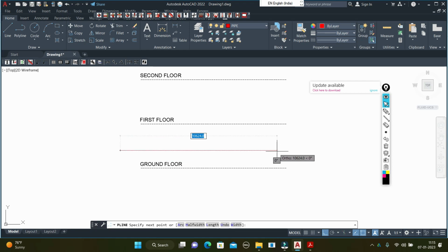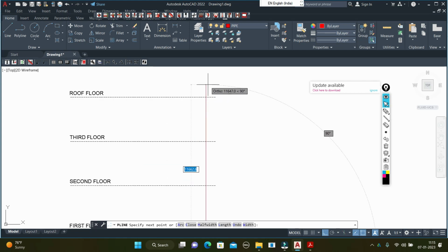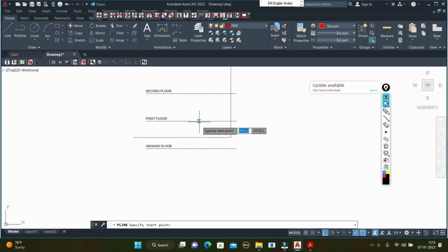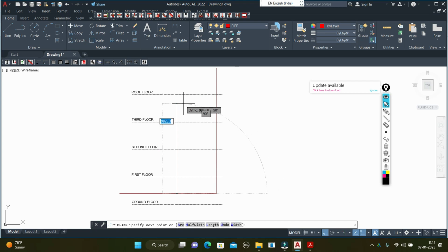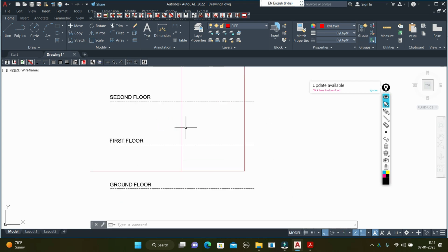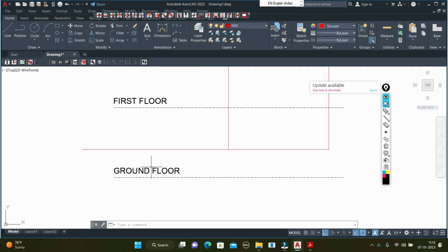So here I am considering that it is two riser. Each floor has two landing valves because this floor is exceeding 52,000 square feet.